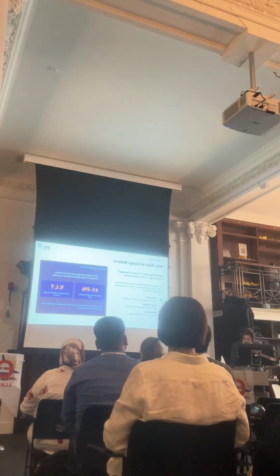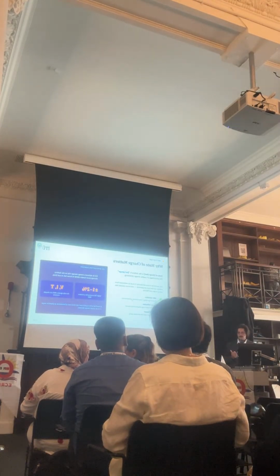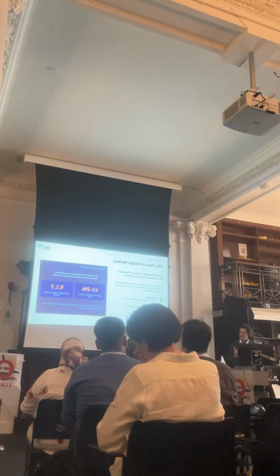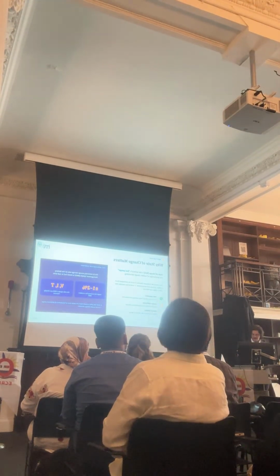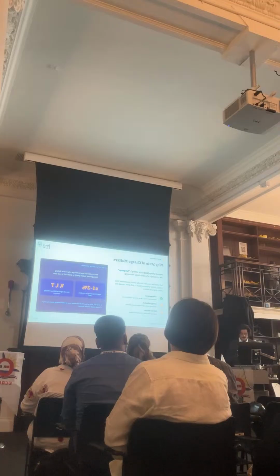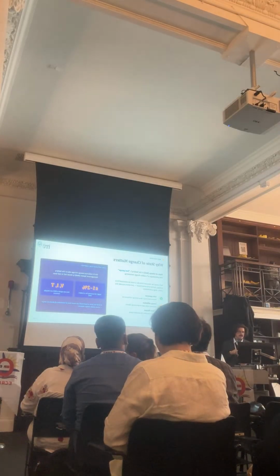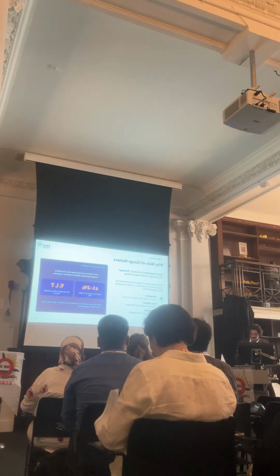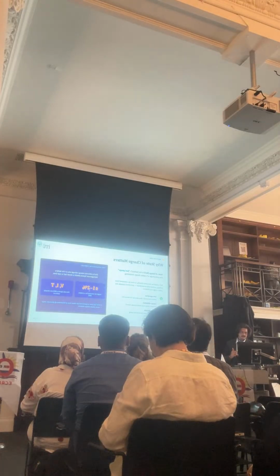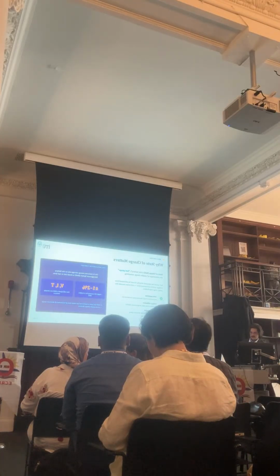And about that matter, the stakes are high. A good estimation protects the cell from overcharging, prevents overcharge, deep discharge and thermal risks, also maximizes usable range and grid storage dispatch, and reduces the stress cycle that accelerates aging. Every electric vehicle and every grid storage system depends on its battery management system, in short BMS. That roughly targets a state of charge accuracy around 1 to 2%, give or take, using only the three signals that we mentioned before.